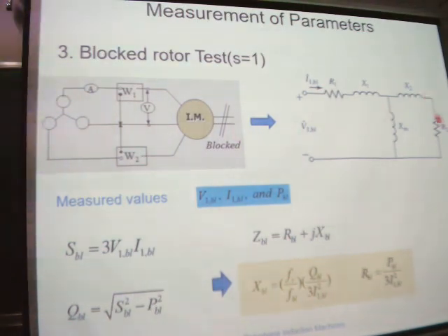It's a low resistance. If we give a large voltage here, the current will be very large. So we can't give the rated or full voltage.